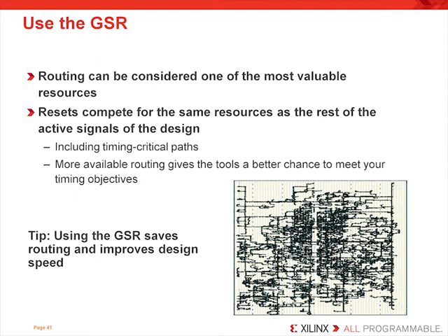A common question we get is, can you migrate resets to the global routing resources? Recall, those are used for distribution of clocks. Well, the answer is yes, by instantiating a BUFG and assigning the reset signal to a dedicated clock pin. But be aware of cryptic messages by the ISE software tools. That's the implementation tools. They will not recognize this as a wise use of the FPGA resources because they're designed to use clocks on the global routing resources.